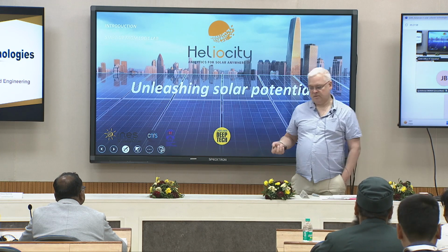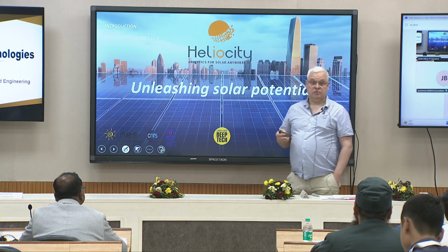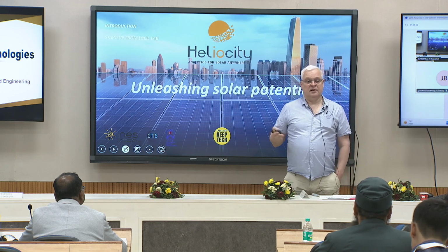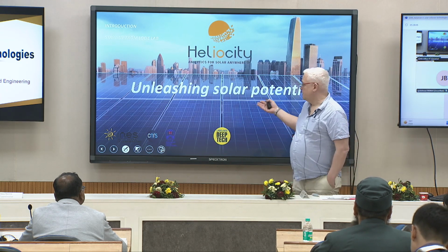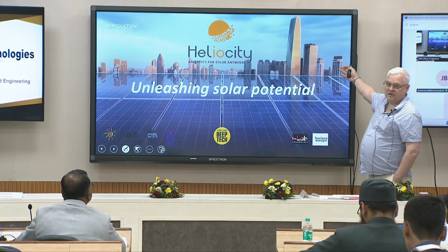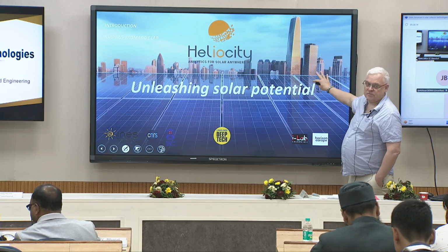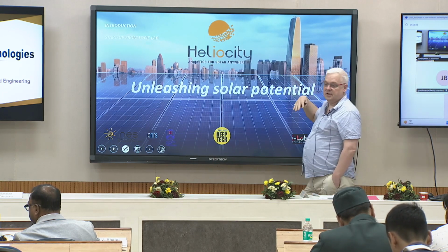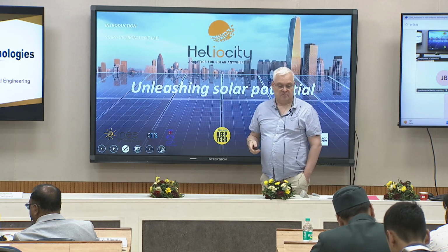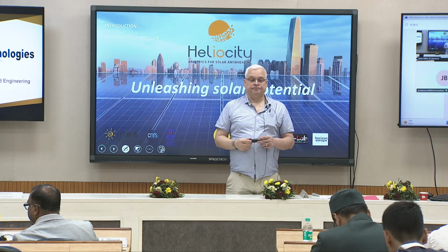Different aspects: you also have shadow. It's stupid, but if you install your PV central and a few years later there is a building, you could have partial shadow and it will not operate very accurately.